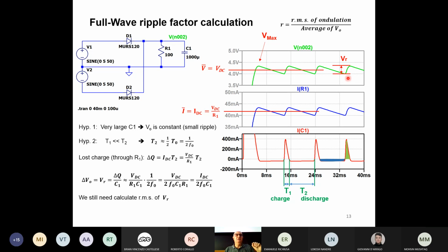They tell you, you turn on the power supply, you put a load resistance, and the system is giving 1 amp of current, for instance. The output voltage will have an average of 5 volts with a ripple of 100 millivolts, or 10 millivolts, or 1 volt. 1 volt is really bad. But 100 millivolts can be the typical ripple for a power supply like the one in a PC. I would not expect anything better than 100 millivolts.